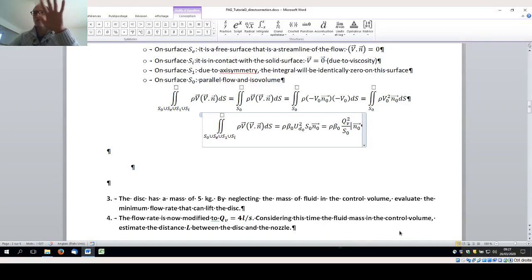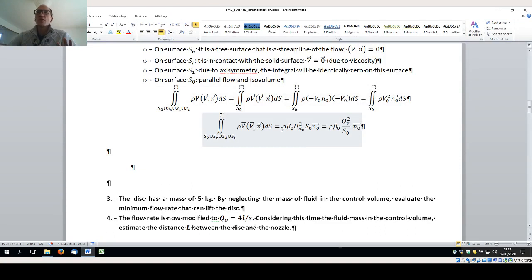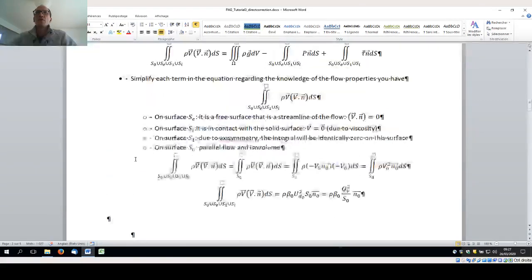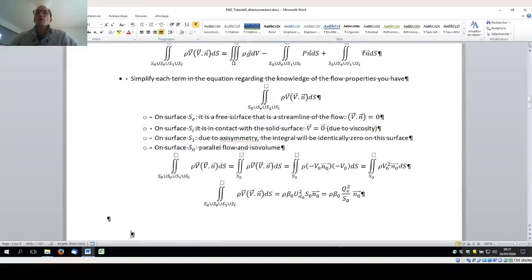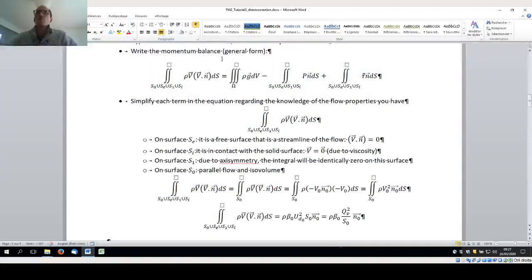So the idea is just to simplify on each section the value of each coefficient, and after in the inlet and outlet sections you use the kinetic coefficient to simplify the integral over velocity square using the mean velocity that I write ud, the flow rate velocity, which is associated to QV, like this. So this first term, this is what it gives.